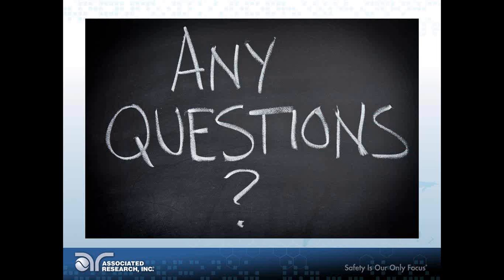All right, so we just got a question regarding setting the current trip points for Hipot tests. Now, I think we covered this in the beginning of the webinar, but just to quickly review it, most standards usually call out for setting the trip limits. Sometimes the standard would call out for just looking at the breakdown, so that's all you need to look at is the breakdown of an insulation. However, it is very important to set the trip limits for leakage current.